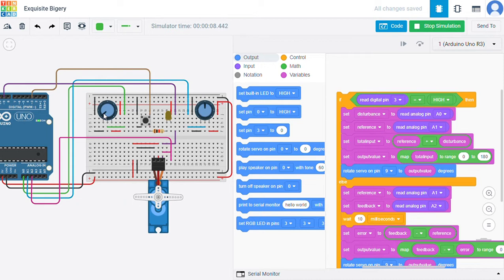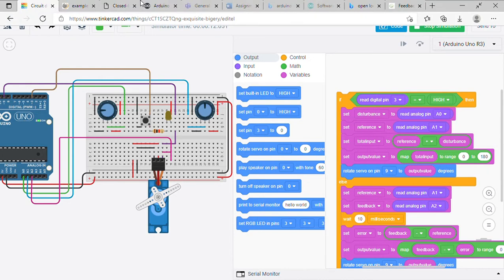But if I create some disturbance and I activate the feedback circuit, now this circuit is taking the input by this pink wire going to A2, and it is detecting the signal with the reference value and measuring the error, and that's how giving the error to the system so that it can be rectified.